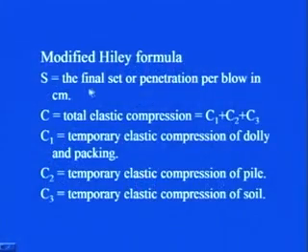Further, S is the final set or penetration per blow in centimeters. See, I told you that you have to be very careful about what exactly is the unit that you are using while you are using these dynamic formulae, because many times when you are taking into account the losses in the energy, you are introducing empirical factors. So you have to be consistent with the units.